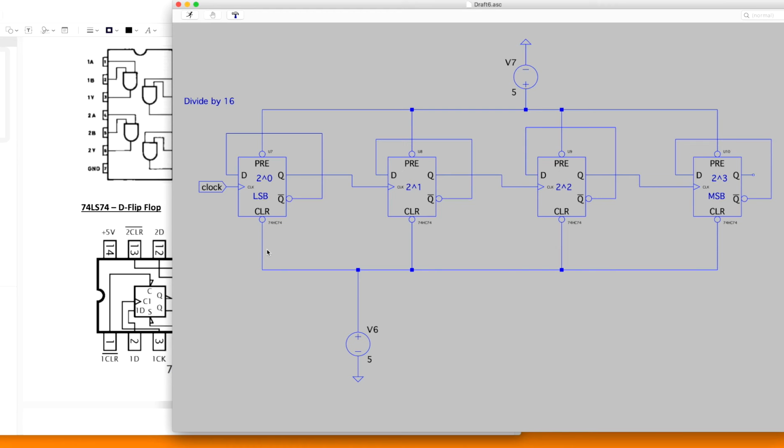Each flip-flop represents an integer number exactly like each bit in a binary number represents some power of 2. The same is true for any amount of cascaded flip-flops. In a circuit diagram, or in a real life circuit, the D flip-flop that has the actual digital clock input attached to it is your least significant bit. It'll represent 2 to the power of 0, which is 1. The next cascaded flip-flop over represents 2 to the 1, or 2, and so on and so forth, all the way up to the most significant bit at the end.